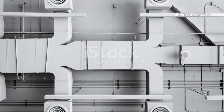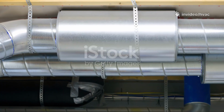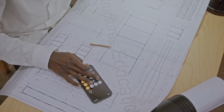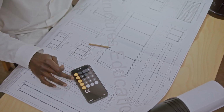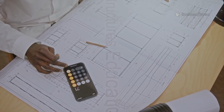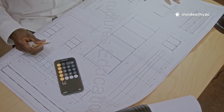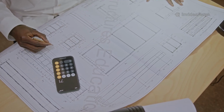Write down the duct's height and width at that spot. Even small differences matter, so double-check your numbers. Step 2. Calculate the cross-sectional area of the duct. Use this formula: area (sq ft) = height (ft) x width (ft). Make sure both measurements are in feet before multiplying.